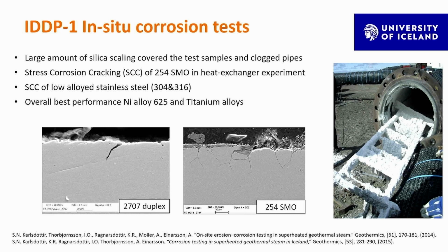And this is not snow, even though it's in Iceland. This is silica, because from the geothermal reservoir, we have a lot of dissolved silica, and when we drop the pressure, this is going to occur. But it was surprising how much silica was dissolved. We were expecting some, but this was quite much more than expected.